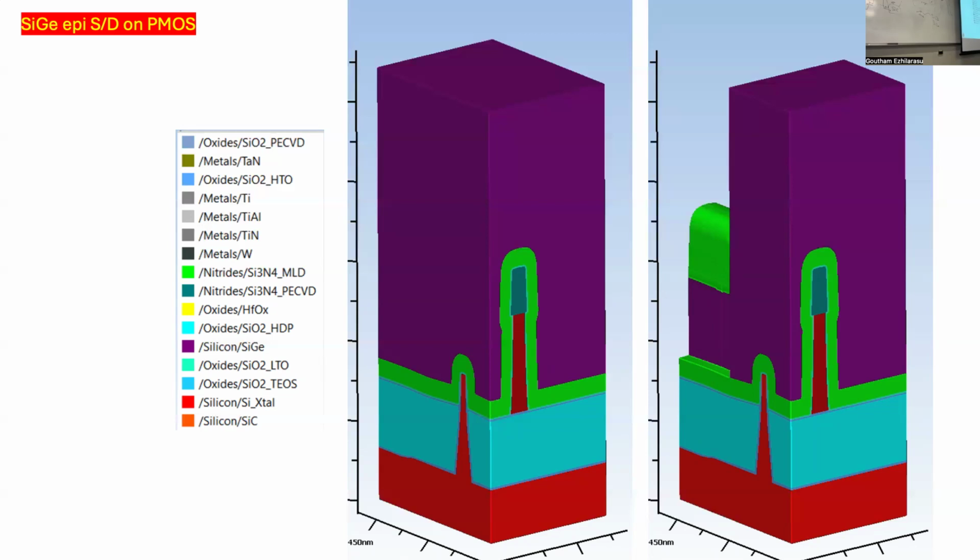No, what do you mean cut? No, I'm not cutting anything. That's what I'm going to explain. I'll explain in the planar case, because it's easier to draw. So what I'm doing is I'm covering all this with some oxide nitride mask, and I'm assuming it's already lightly doped. I've not shown that, but you already create the lightly doped region. But now what I'm going to do is put a mask, okay?